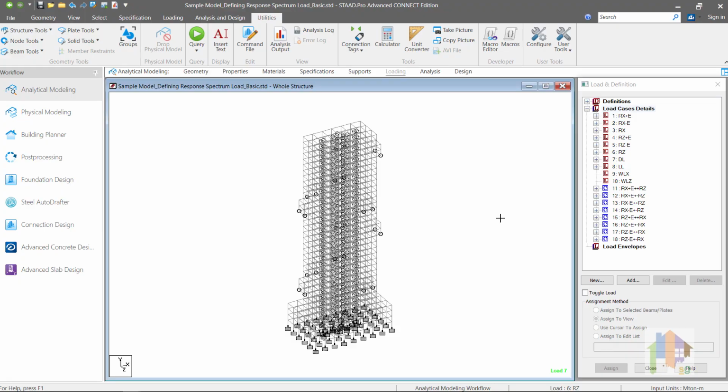To consider this factor in analysis, there are two approaches. Either we can create 8 new load combination cases where the existing dynamic load case is multiplied with this factor. Else, we can use this as the combination factor for seismic load case during combining with gravity load cases.